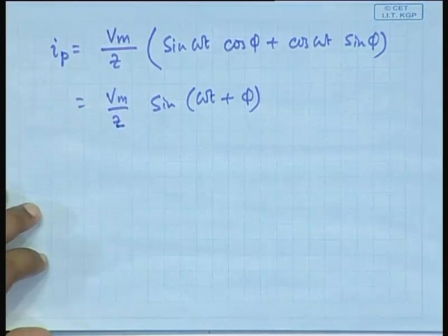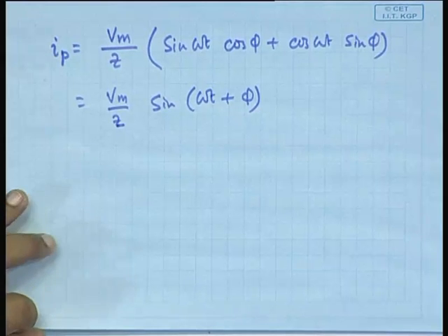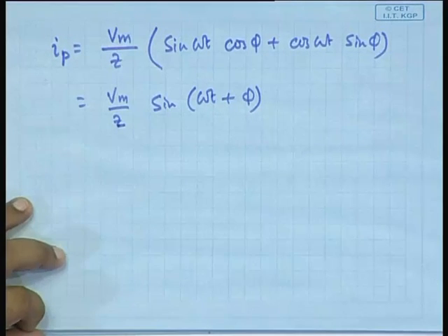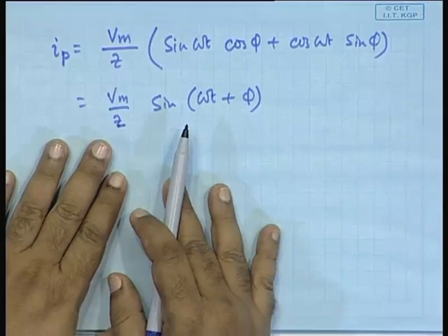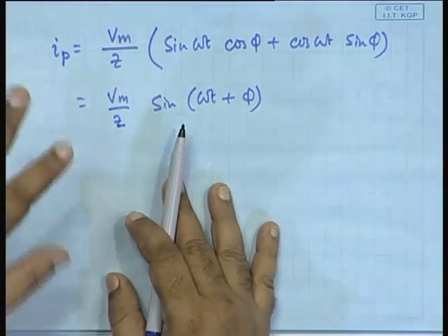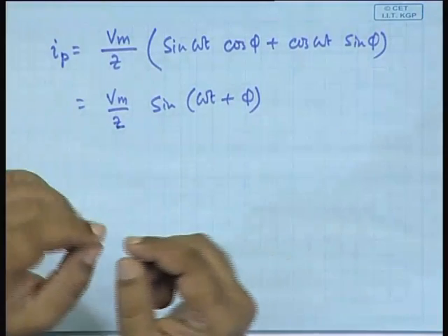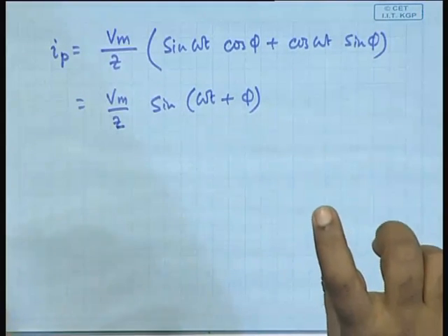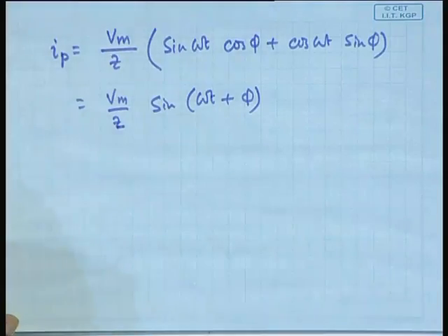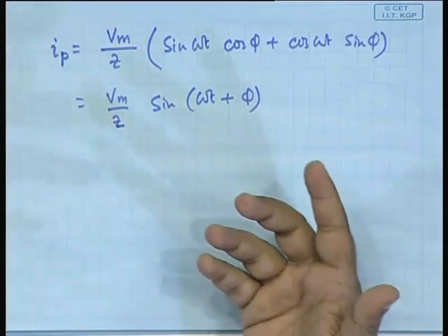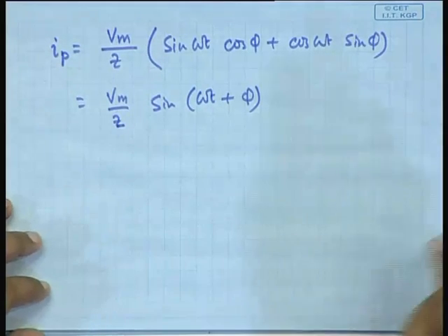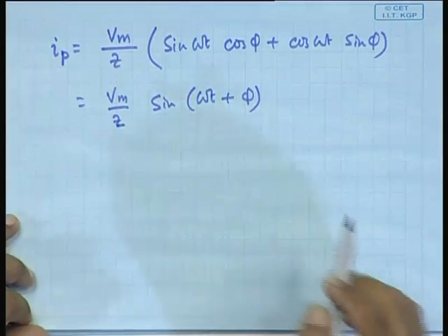So, this is the particular integral. What about the complementary function? See, obtaining the steady state solution is not difficult, because you already know that if you have an RLC circuit, the way we do in electrical engineering is that R and then j omega L, 1 by j omega c, add them, obtain it, you get the same thing. So, here so far I was writing a bit faster, because this is something that is already known. What about the complementary function? That might give you trouble.